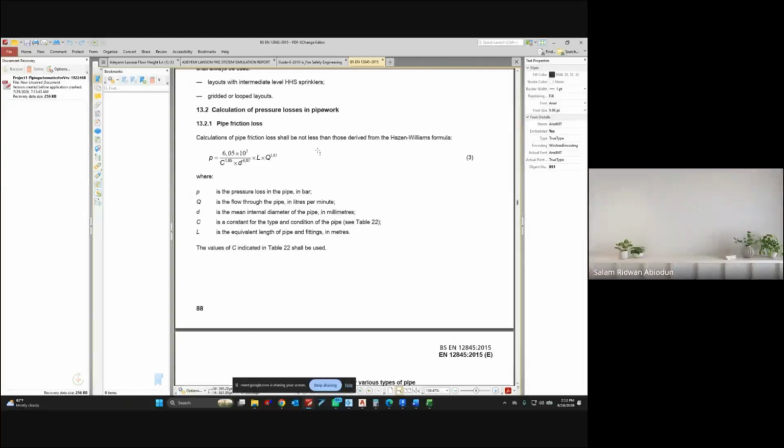I will now make it a constant, like I will say 6.05 exponential 5 divided by 120 raised to the power 1.2. I will now leave the D, the L, and the Q. The Q2 will vary. So I will now be using it to multiply a factor that we get when I use length to divide the diameter and multiply it by the flow. Do we understand what I'm trying to say?